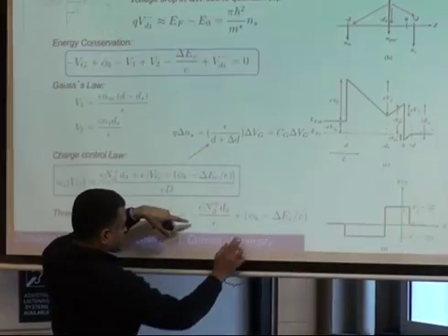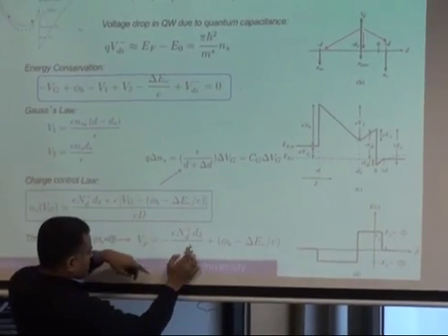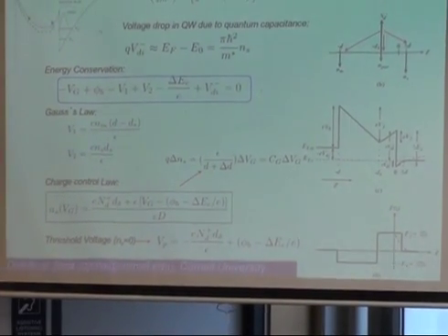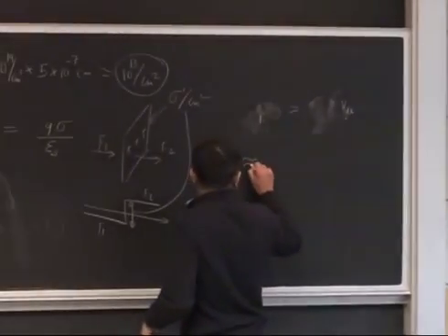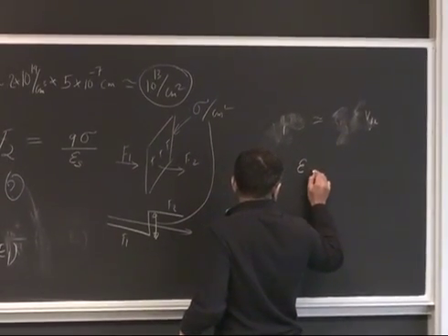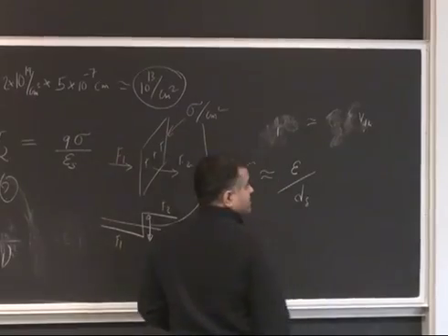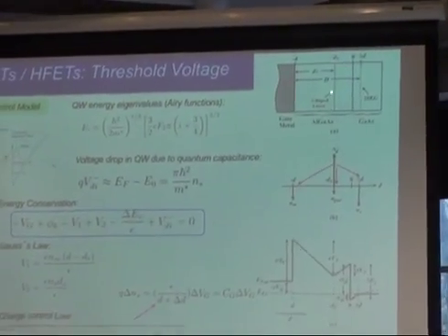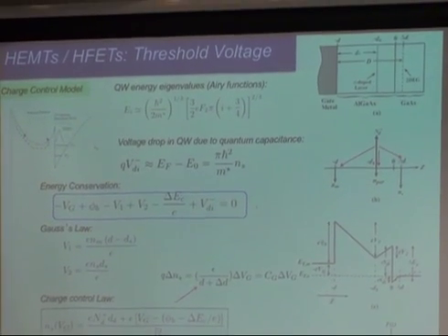And the capacitance that appears here, if you forget about the band offsets and other details, is basically epsilon by d delta. Now that's your capacitance that appears. Dielectric constant of the semiconductor divided by d of delta. What is d of delta? Looking at this picture, it's basically the distance you put your delta doping layer from the surface. That's roughly the number.